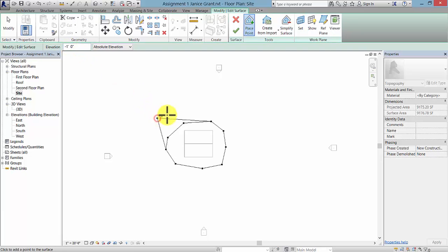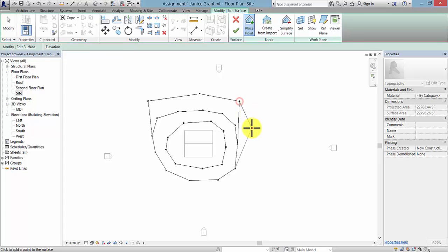And then out here in space, we're creating our next elevation level. So this is how you can start to create contour lines on your site. You can change this to something even different, maybe -2, bringing it down just a small distance away.